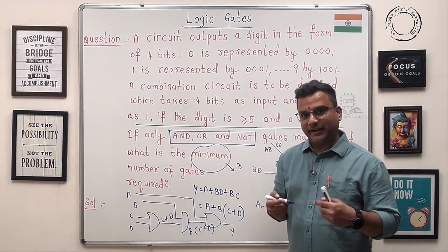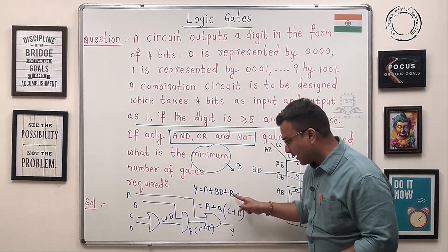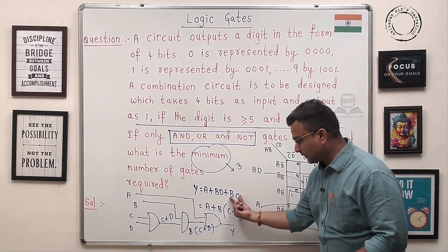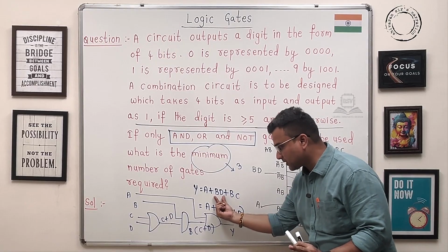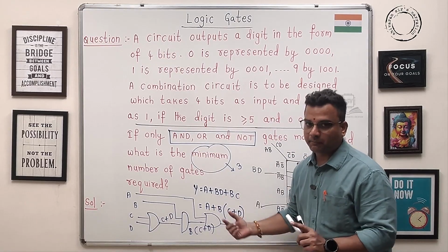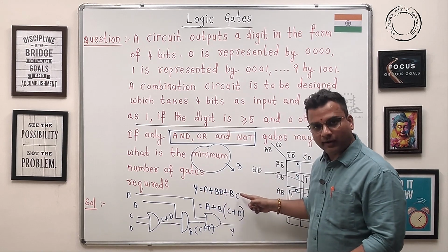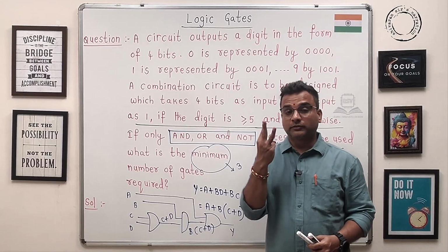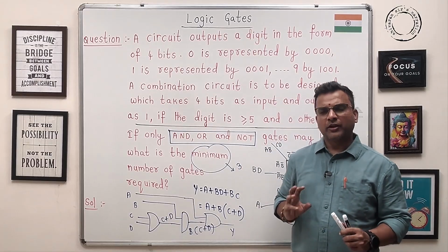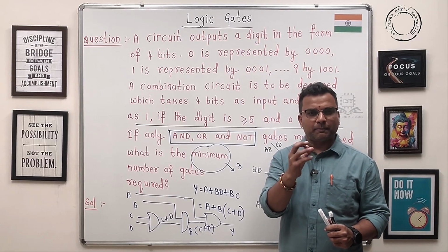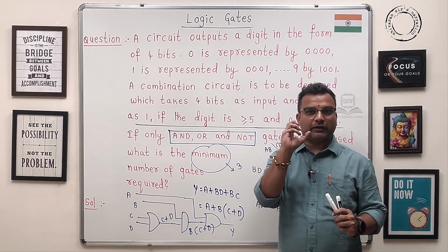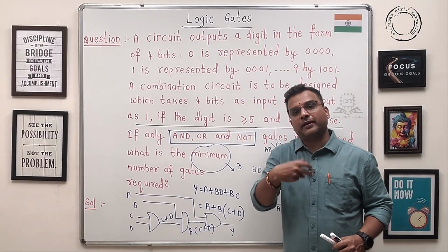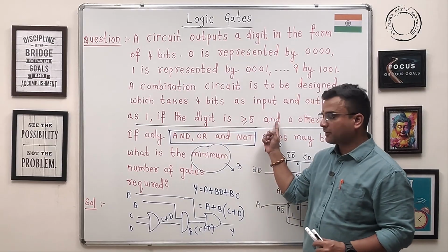Even, guys, you might say, sir, I don't want to take the common, I want to write A, B, D plus B, C only. Then for this you require one AND gate, for this you require one AND gate, but still to OR all these terms you need an OR gate. Of course, that time you require a 3-input OR gate, right? Usually you need to consider the minimum number of inputs for whatever the logic gates, right guys? This is about the simplified implementation as per the design requirement.